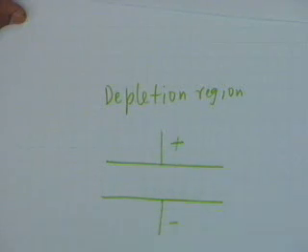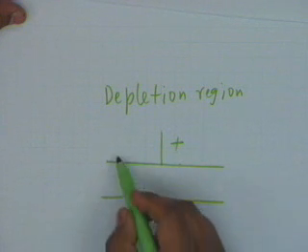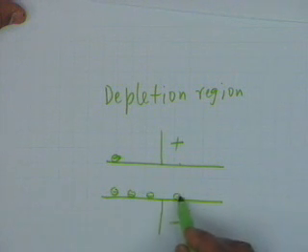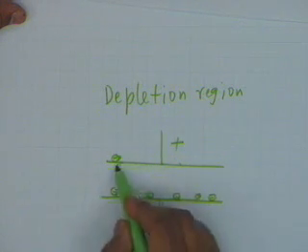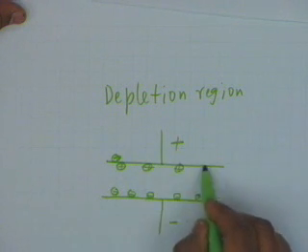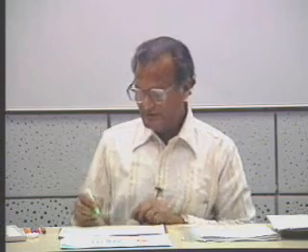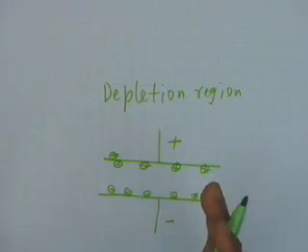If you make this potential positive with respect to this, then this positive charge attracts electrons on the surface of this, the negative potential attracts positive charges here, and therefore there are equal and opposite charges separated by distance, and therefore the depletion region then acts like a capacitor. Is that clear? The depletion region acts like a capacitor. There are negative charges on the left hand side, positive charges on the right hand side, and whenever this situation occurs, there is a separation of charge.